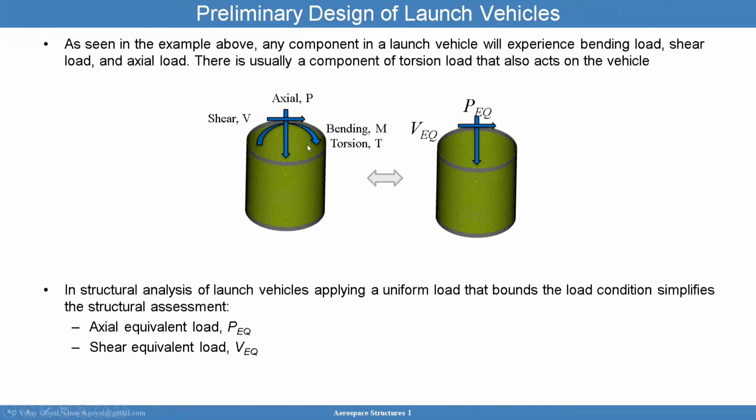Why is that? So let's look at this. So when I apply an axial load in compression, say, the vehicle will be mostly in compression, and I apply bending, this side will be in compression and it's going to be additive. So you're going to have the axial load plus the bending load, which is going to cause compression on this side. Well, on this side, you're going to have axial load and then the bending is causing tension here.